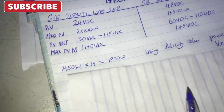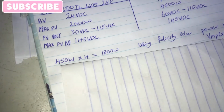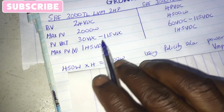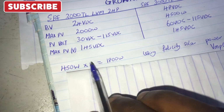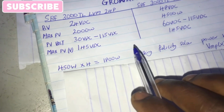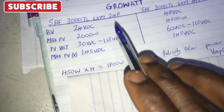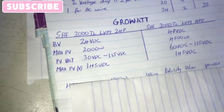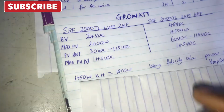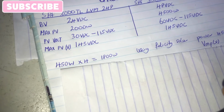So using this, we are using 450 watts. For the connection we are going to use, because of our maximum PV volts, we cannot go more than 145 volts. But it is clearly stated that the PV power volt should be 115. What we have here is 40 volts. To be on the safer side, we are going to use 2 series for this calculation.